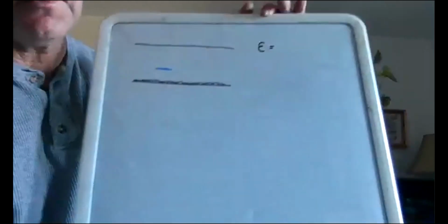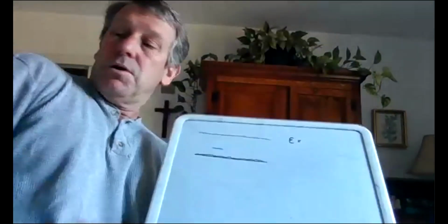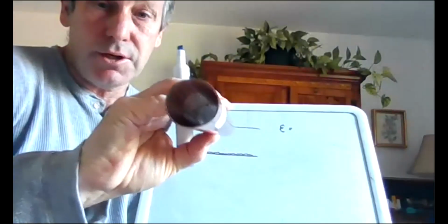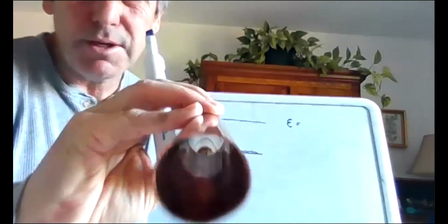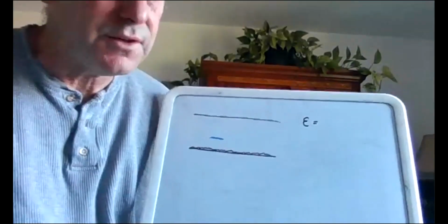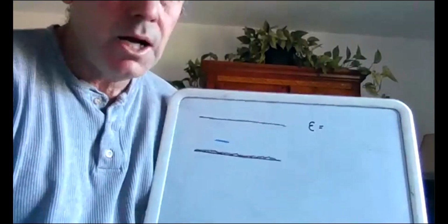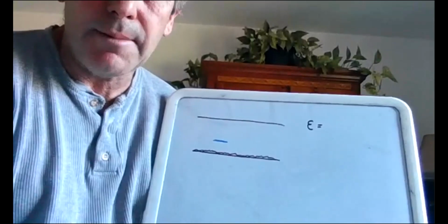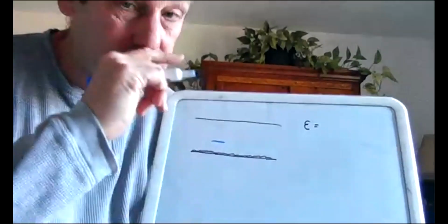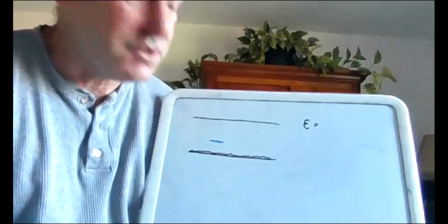All right, pipe roughness. Ordinarily you think of a pipe as being nice and smooth on the interior, and copper pipe is pretty good, but if you look closely at it, you might see some things that contribute to some roughness. And obviously roughness is going to contribute to friction, just as in your normal dynamics. In dynamics, we measured friction with a coefficient of friction. Relative roughness is similar to that.